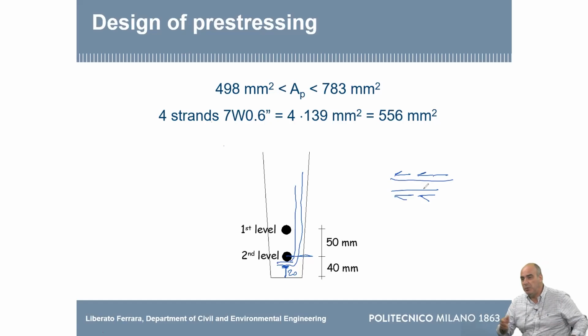In precast, we generally do not use large aggregates for these elements. We might use maximum aggregate in the range of 15, 16 millimeters. Then it depends on the national tradition what size ranges you go by. We go by 4 because that is a transfer of the inch number of the sieves that you have for the aggregate grading, but 16 millimeters. So 16 plus 5 is 20.